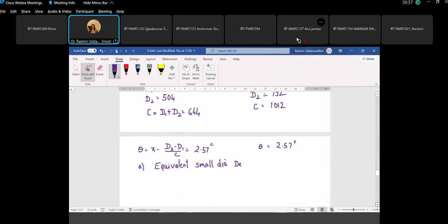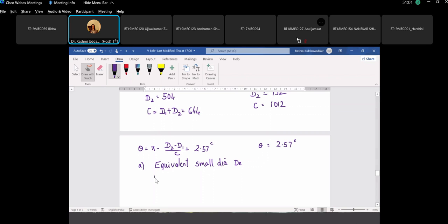For both B and C, give me the ratio D2 by D1 and accordingly refer to the design data book, page number 7.62. Your value of D2 by D1 would be normally greater than 2.9. Is it 3.6 for both of you? Okay, that is the same because it is equal to N1 by N2.